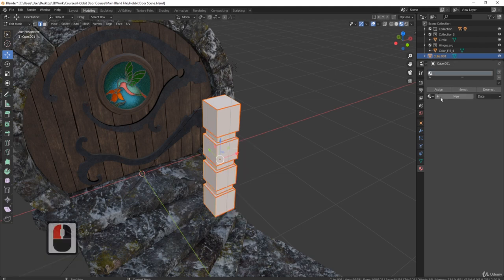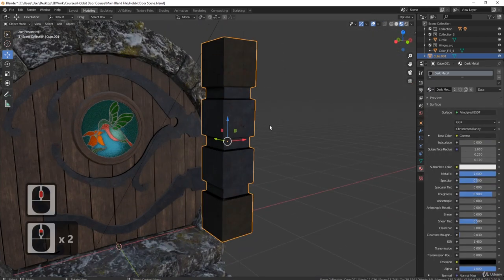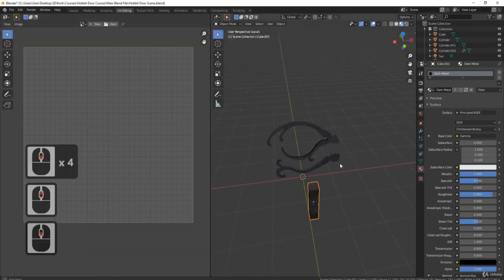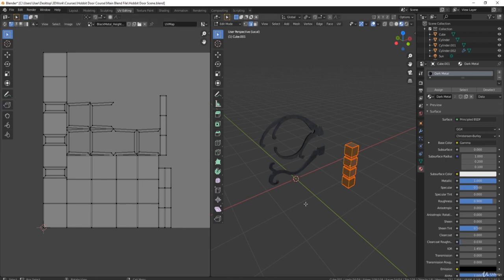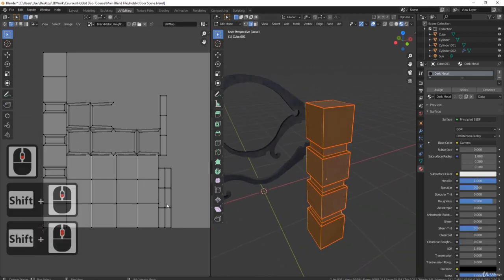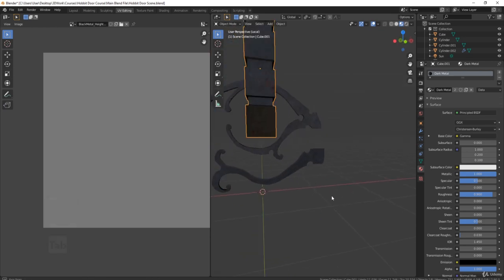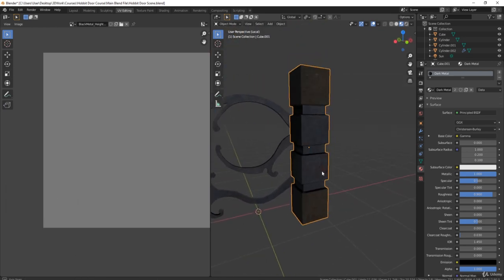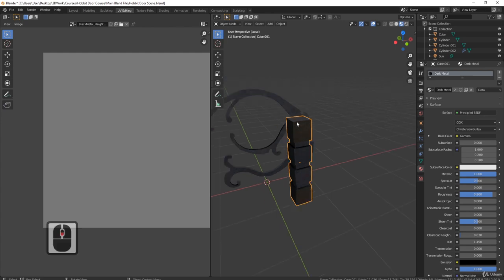Let's now press the plus button, press the down arrow, and what we're going to look for is dark metal. So let's bring that in. And then what we're looking for is just to make sure that you're happy with it. Let's go over to our UV Editing panel. Press the Tab button and let's zoom out and just make sure they're all in the right way. You can see they're probably a little bit too big on this UV map, so I'm going to grab them all, shrink them down like so, and just make sure that you're happy with them. And finally then, now I've got them in place, I want to bend this. So I want to bend it to get it in place.